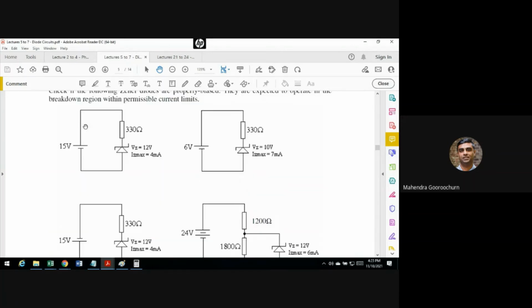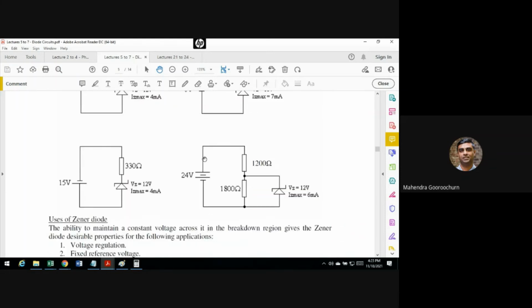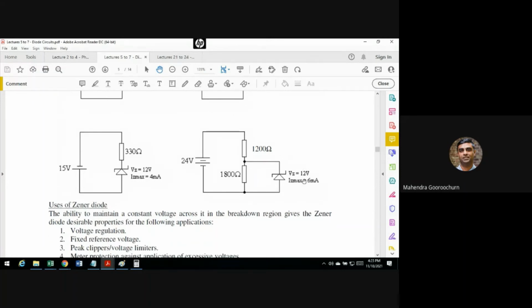Okay, so we've seen this one, the problem is about the current. This one, the problem is about the voltage. This one is the problem about the polarity. Let's look at this last one here, and we end for today. If you look at the polarity, first, the way it's connected. If you have 24 volts there, current would try to flow like this. You can see these two are in parallel, so current is going to split into two here. The same main current has to flow here and then get split into two, and then would flow here.